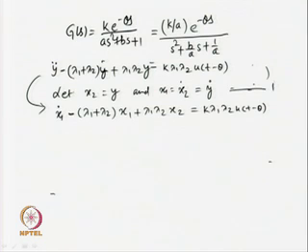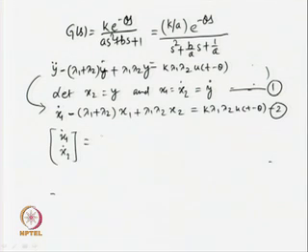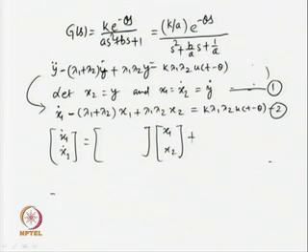Now, let this be equation number 1 and this be 2. 1 and 2 can be used to get the state equation now. So, allow me to write that further, x 1 dot, x 2 dot is equal to the matrix times x 1, x 2, plus for the input we will have u(t minus theta). So, this is the way one can write the state equation.